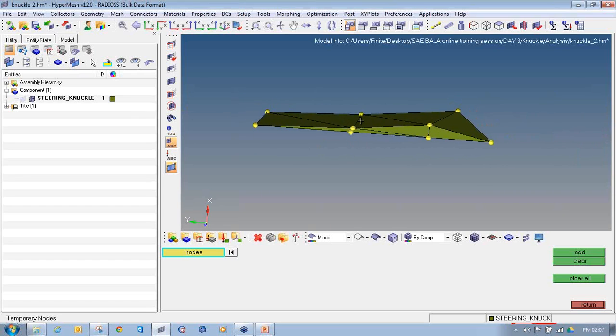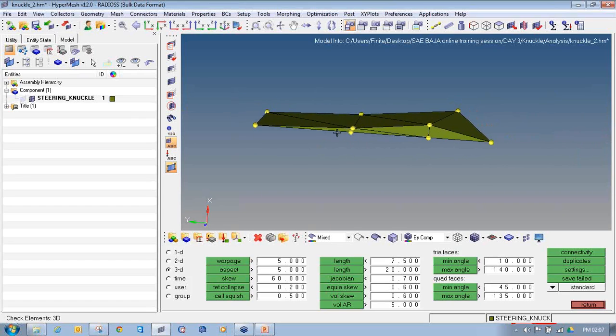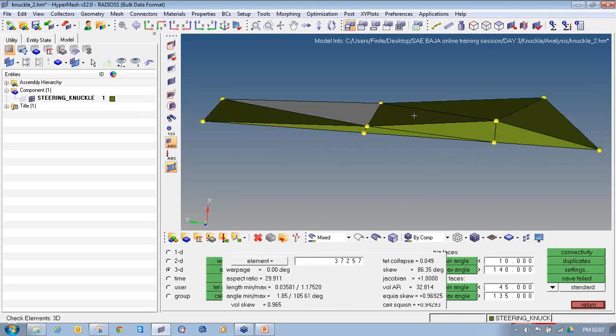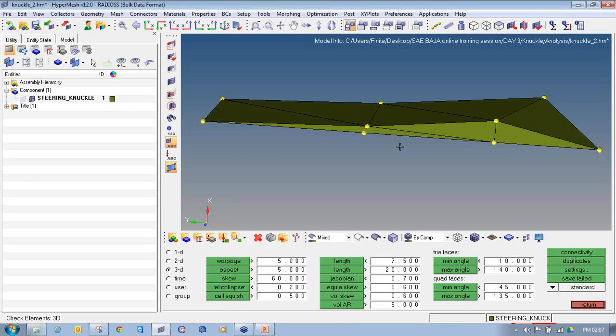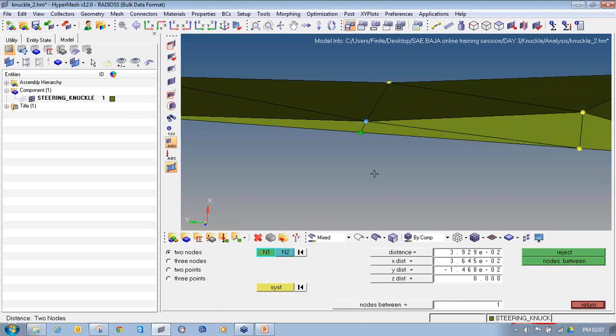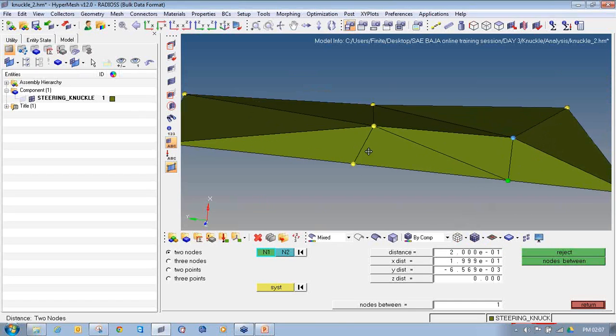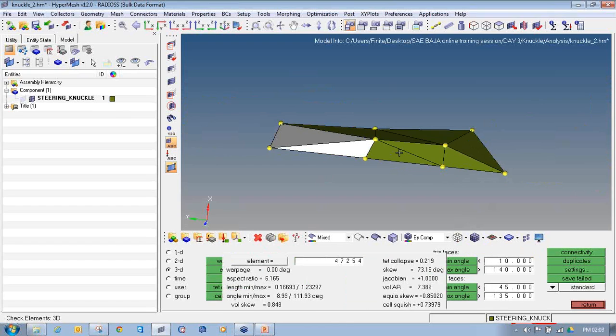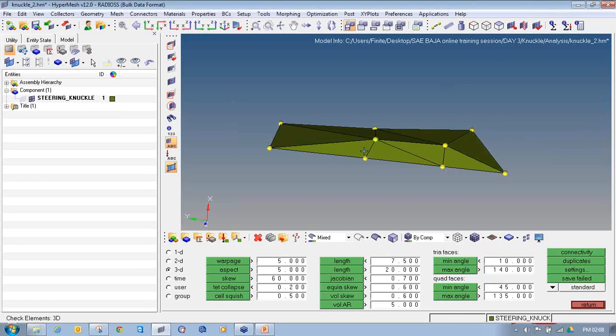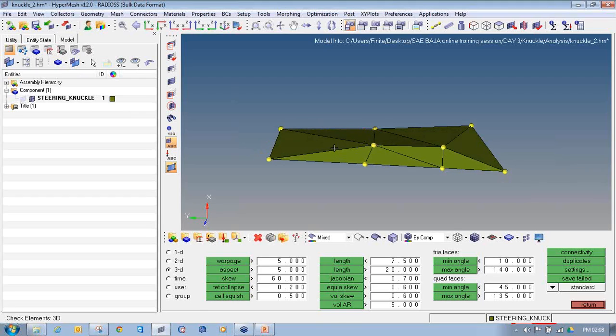So this is because of this height. So I will again improve this height. First check what are the aspect ratios. So it's 29, 29, 9, 21, 6, 9. So I will change it to 0.2. This one also as 0.2. Then press F10, 6, 4, 6, 5, 5 and 3. So I will just decrease this length.